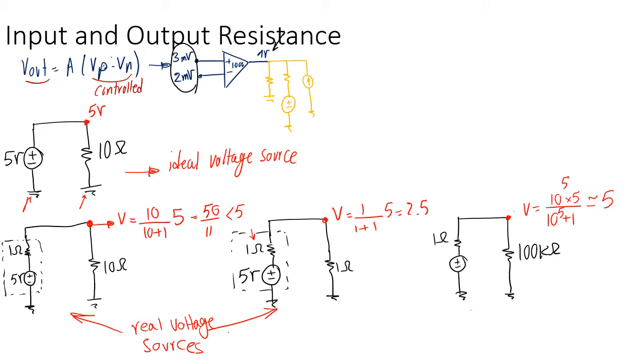So ideally, in reality, we do have a little bit of internal resistance, to be fair, right? And it is very tricky to design a voltage source that doesn't. One of the most important parameters for a voltage source is to make sure that the internal resistance, or the output resistance, the resistance that we see at the output of the voltage source, is pretty much 0 or minimized, right?